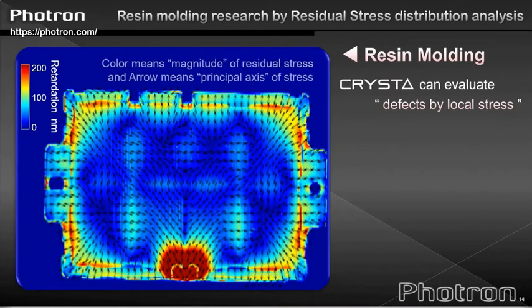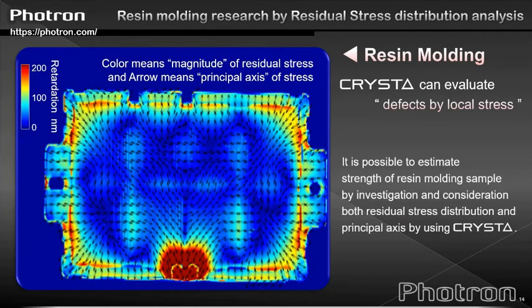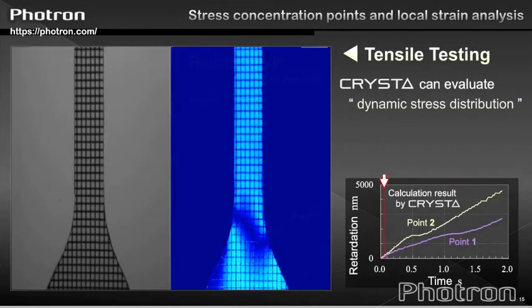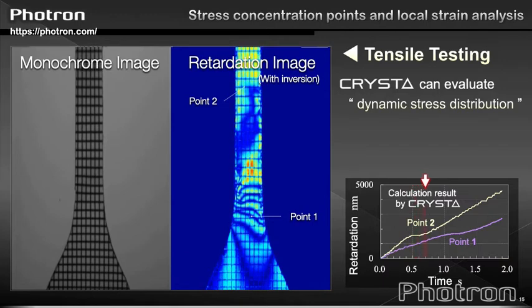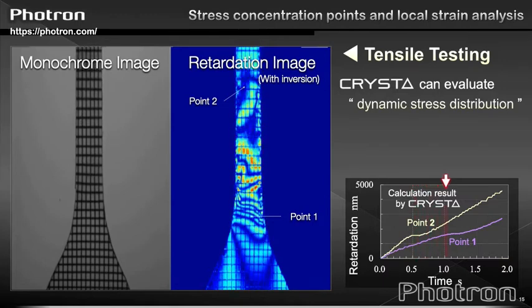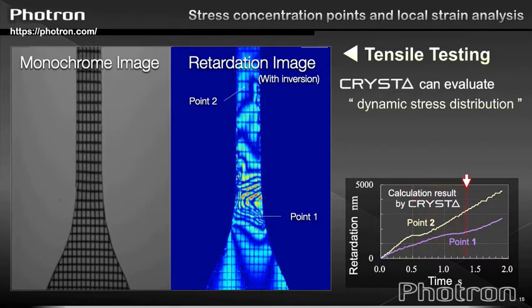As long as the material being studied is birefringent and transmits a minimum of 30% light, the CRYSTA and its static scan brethren can be used to visualize both dynamic and/or residual stress. With lightweight plastics playing an ever-expanding role in a wide variety of fields, the ability to assess and understand how these materials perform is critical.